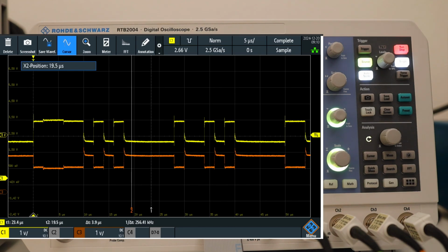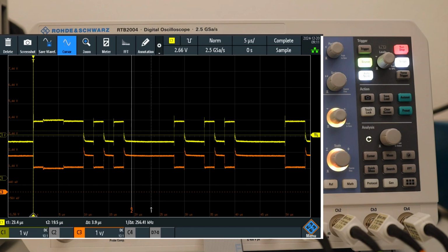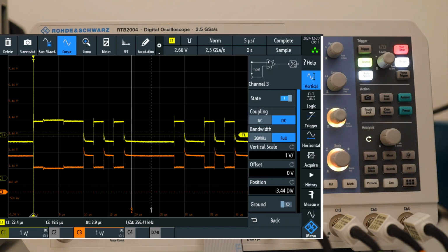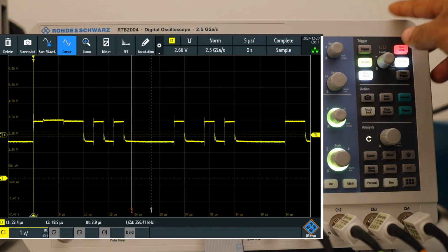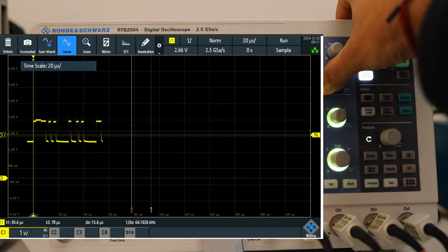We are not here to discuss the electrical characteristics of the CAN. You must just understand that for decoding you primarily need CAN high or CAN low. The decoder can be set to decode from either polarity, and we normally do not care about both of the CAN signals. Normally we can ignore the other CAN signal. I'll disable channel number 2 and let it run from channel number 1, and we will set up a decode there so that you can see a little bit better.